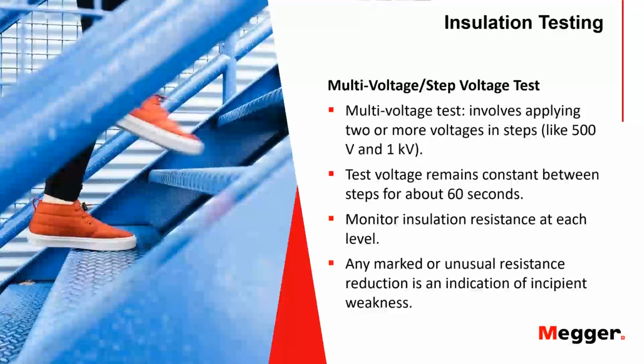Okay, with a step voltage test, now you can design your own based on what your equipment can do. But the industry standard is to increase your voltage every minute for 5 minutes. And equipment that's set up to do step voltage test automatically will simply ask you, what is the limit? How many volts do you want to go up to?